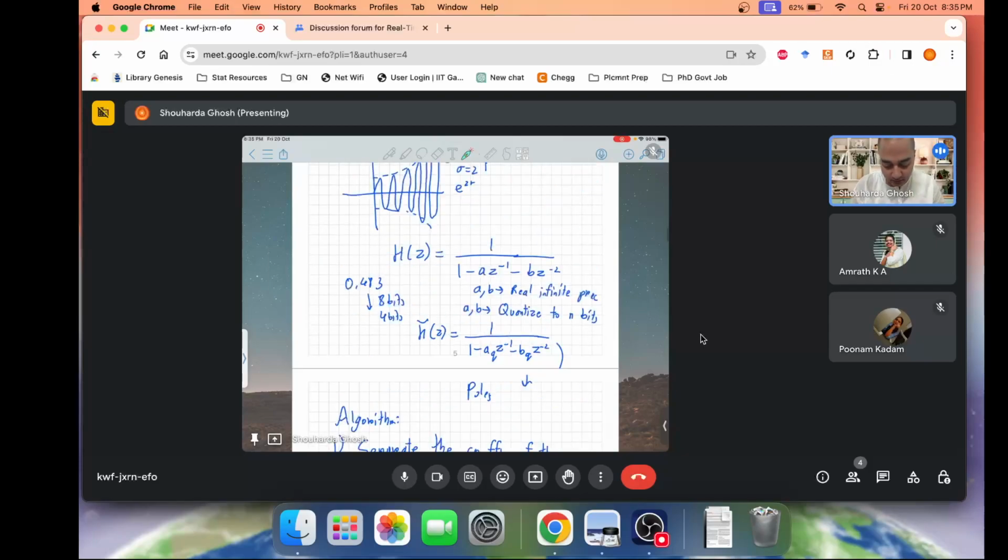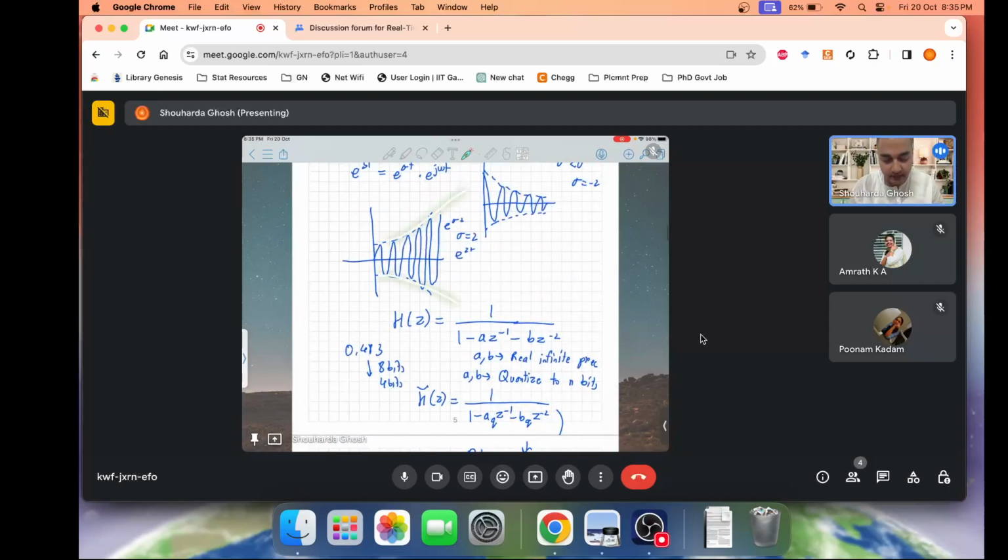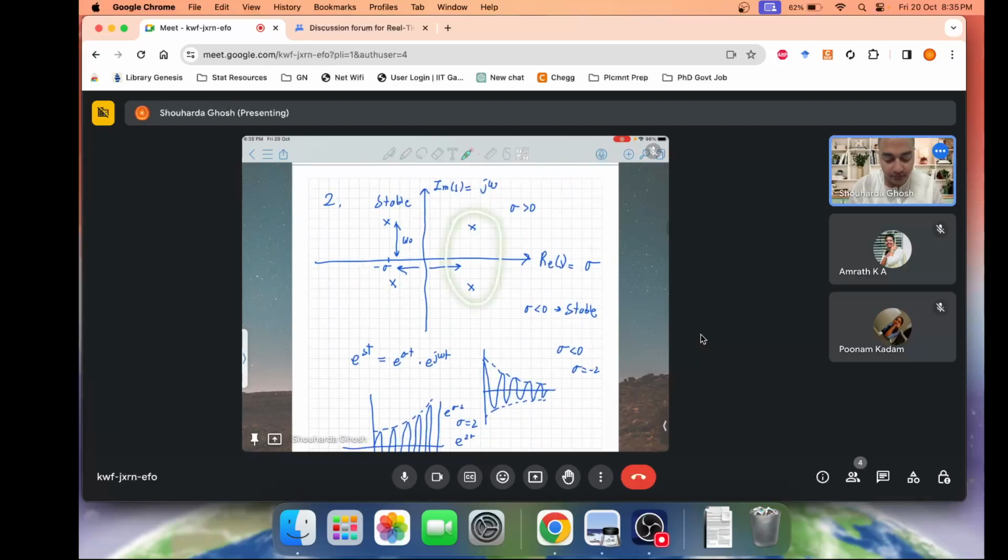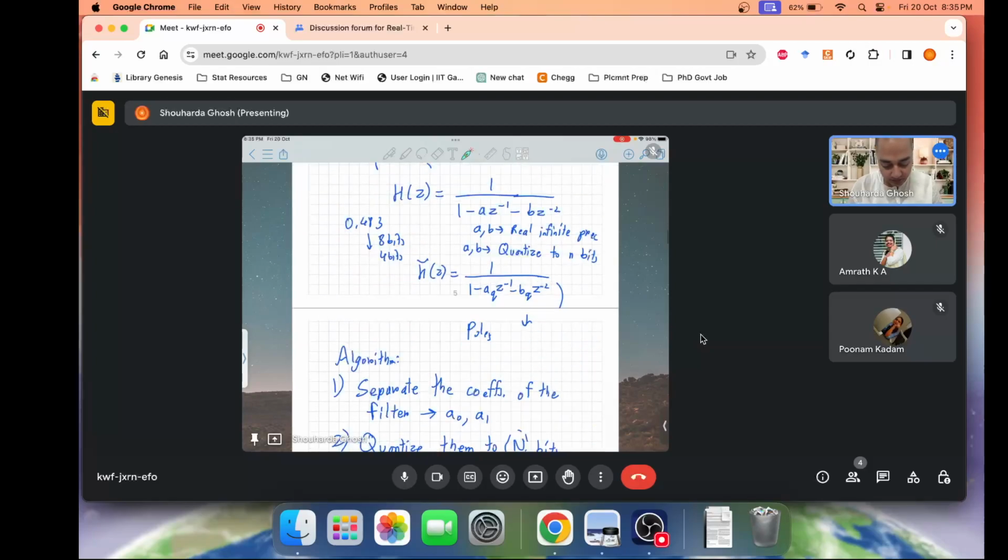On the other hand, if you look at the rising case, for an impulse input you have exponentially scaling outputs, which is an unstable system. So on the right half we cannot afford to have poles; we have poles in the left half. That's good.